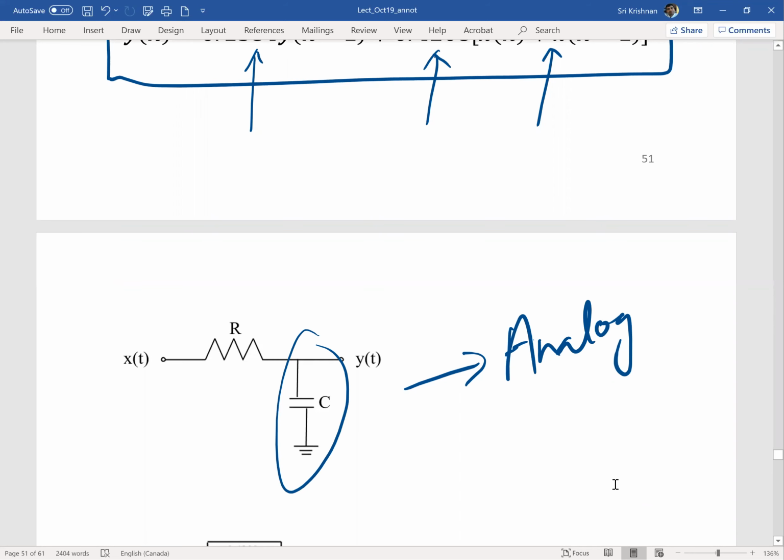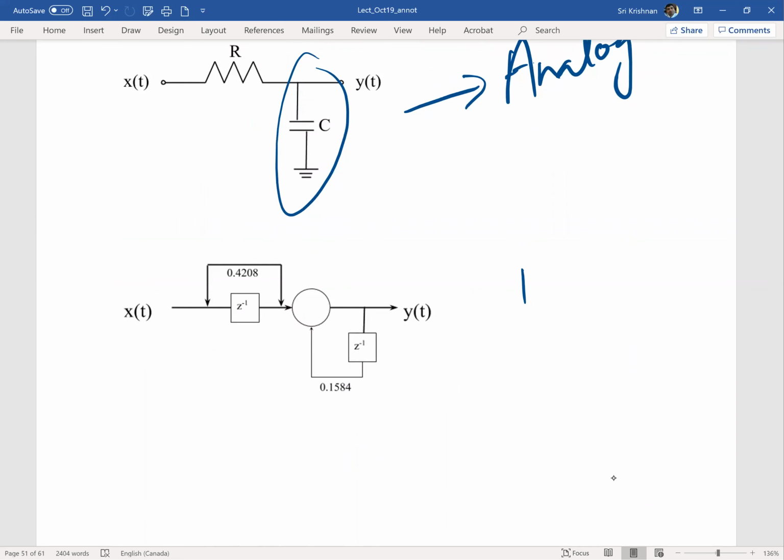And an equivalent version of the digital filter, as we just discussed, involves the filter coefficients. So we have the filter coefficients here, and also this 1 is going directly into it. Okay. So to be more accurate, I think I should have made this x of n and this y of n. Sorry. So it's x of n because it's all happening in the digital domain now. So these are basically the digital filter coefficients, and this hardware configuration of the RC circuit has been converted into a digital representation like what's shown here. Okay. So that's the neat thing about the design.